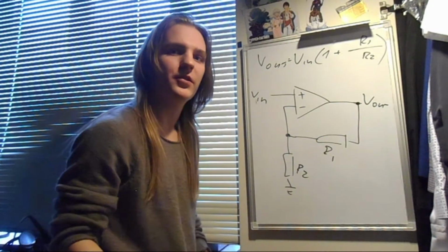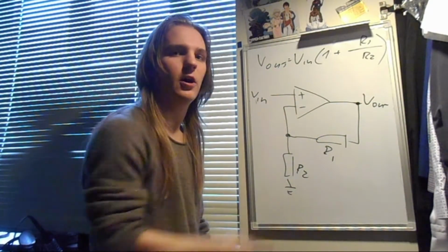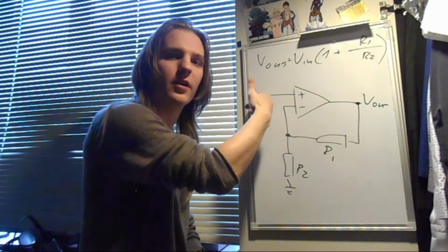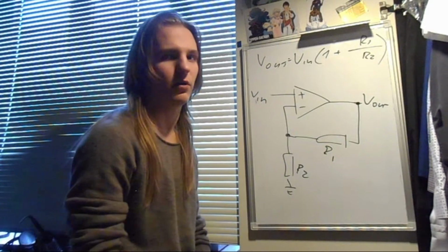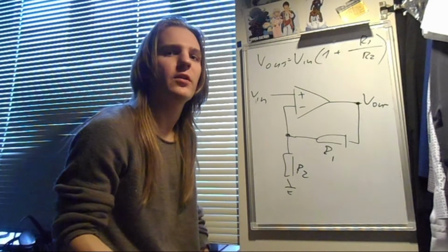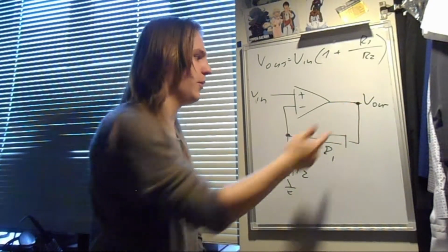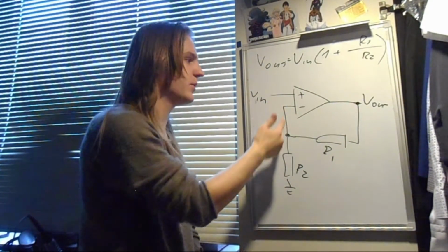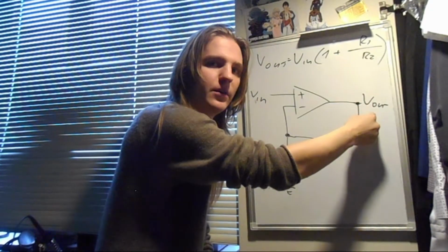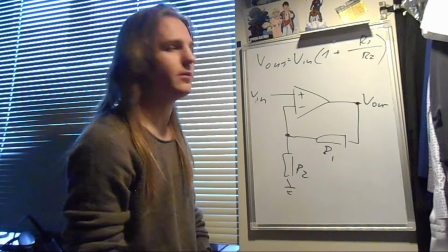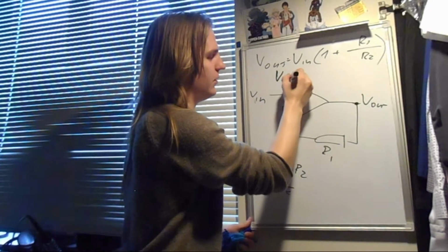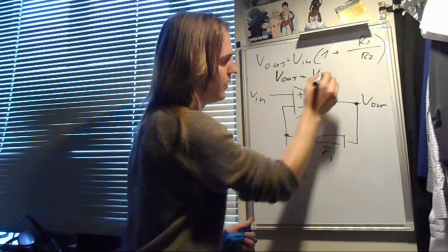Why would we need this? Because the operational amplifier almost draws no current, so simply current does not flow into this thing. And we can use this to buffer our voltages, so if we say need like 100 milliamps of power right there, but only have 5 here, we can put our source, which can only give 5 milliamps, here. Its voltage will be copied right there, but it will be able to supply way more amps. So this thing gives us V out equals V in.